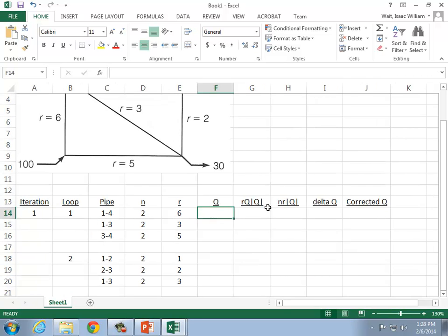Okay, so the cues that we put in initially, we could do a flow balance. There's nothing magical about these ones that I did. We'll go with it for now so that we can check against what's on the board. But later on, we'll adjust the flow rates to something crazy like 1 and 99. And it'll still converge eventually as long as you honor the continuity equation. Well, let's stick with a more reasonable guess.